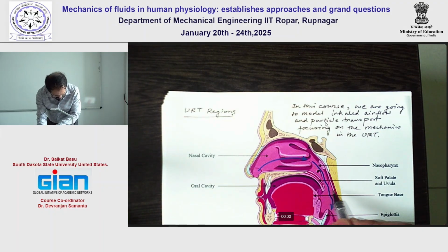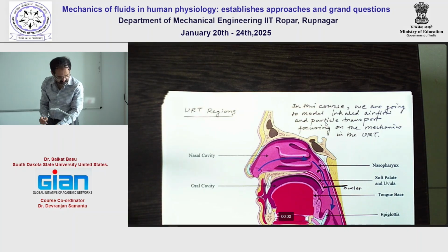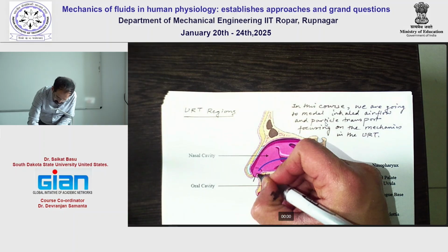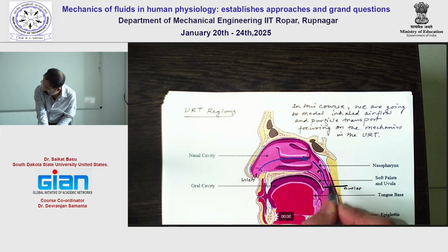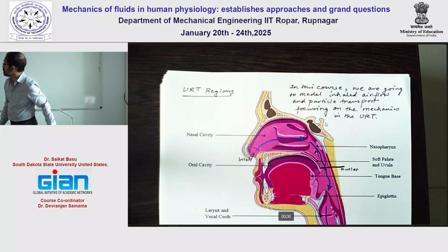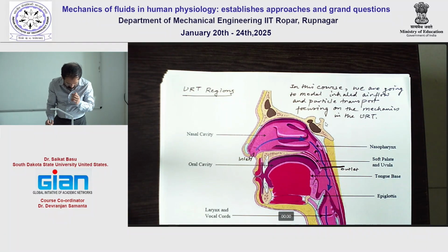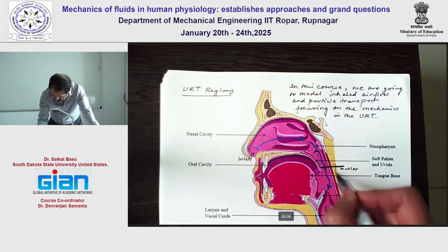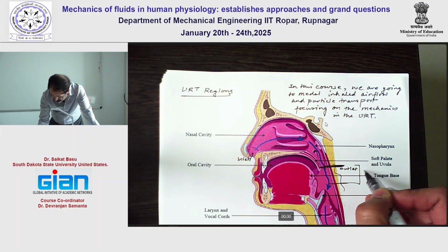The geometry that you are going to see would have its lower extent as over here. So the outlet for the flux, and the inlet would be at the nostrils. So this would be the inlet. The air goes all through, and it escapes the geometry that I've built for you guys through this outlet. Now the oropharynx is this region. Basically, this part is the oropharynx.